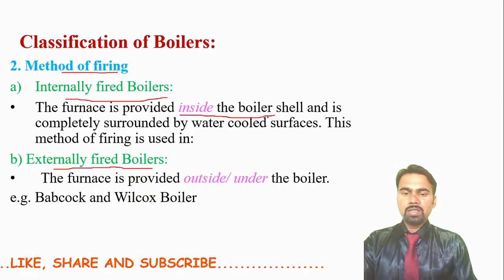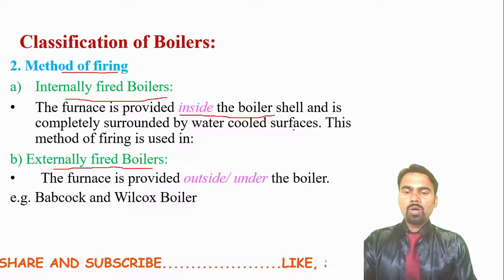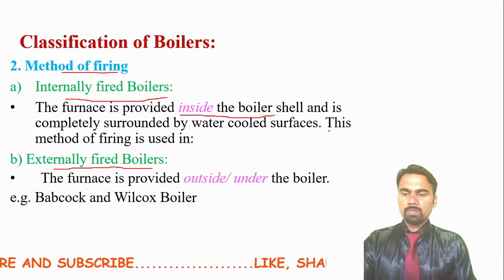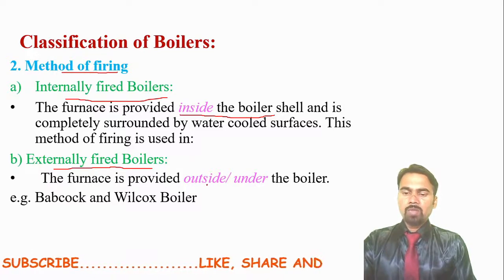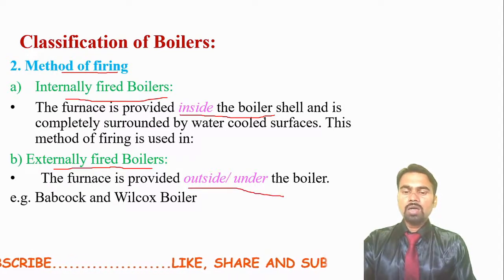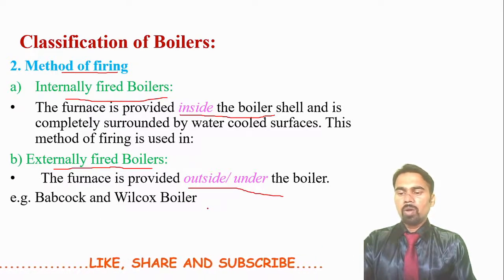Furnace is provided inside the boiler shell and is completely surrounded by water cooled surfaces. Okay. Then externally fired, where the furnace is provided outside or under the boiler. It is not the part of boiler shell, right? So example is Babcock and Wilcox boiler.